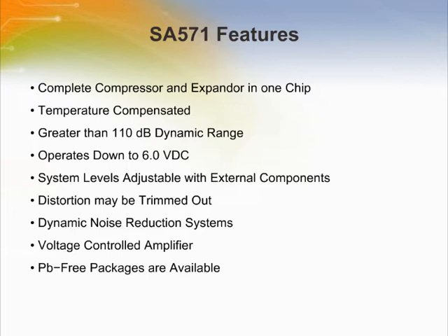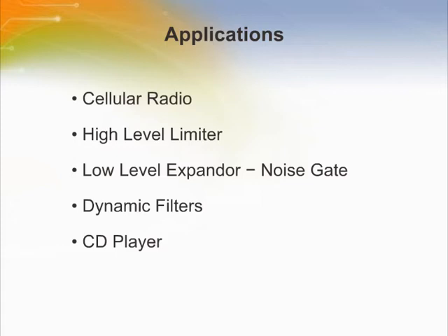It is an inexpensive integrated circuit which offers a pair of high-performance gain control circuits featuring low distortion, typically less than 0.1%, high signal-to-noise ratio, about 90 dB, and a wide dynamic range, about 110 dB. This compandor is well suited for use in modems, telephones, cellular radio and radio communication systems, as well as satellite broadcast and receive audio systems.